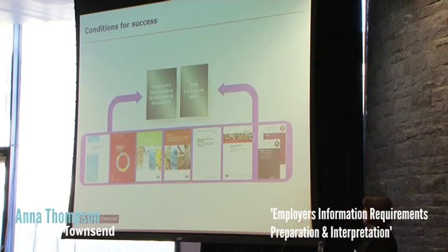So, conditions to success. Well, in the UK, we use all these documents: the PAS 11922, PAS 11923, BS 11924, which is data structure, CIC protocols. But what we also do from a cost management perspective, and in the UK we have NRM, we're communicating as cost managers as well what our expectations are of the model.